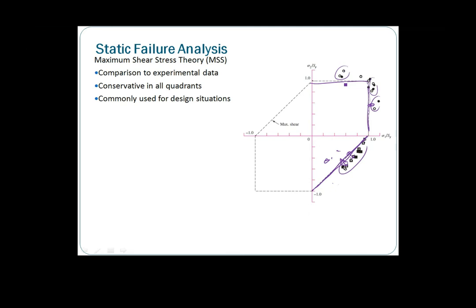So probably this MSS is good because it can predict failures far earlier than the actuals, because it's a little bit far away from the actual. Meaning, if your stress happens here, all safe, right? But in actual, it happens when your stress is at a slightly larger number, only then will it fail. So it's what we call conservative. All right, so that is MSS.